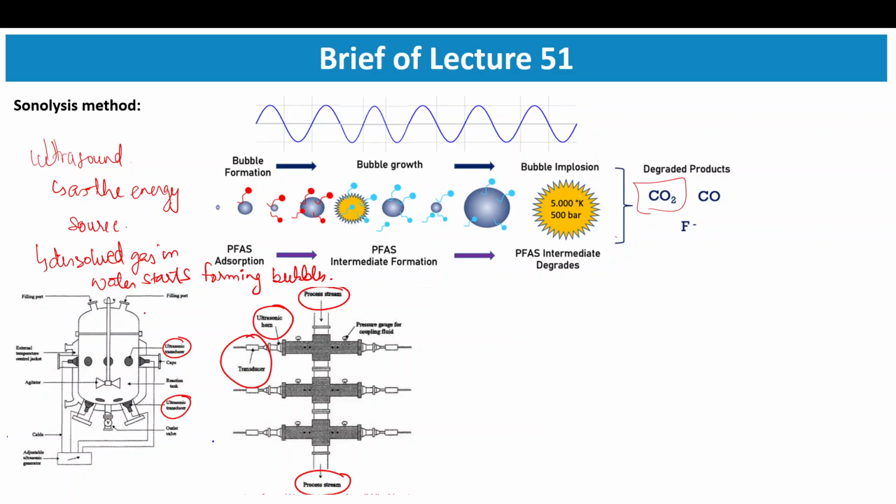In this third tank, you have process water or wastewater, and on generating ultrasound through the various transducers, you allow continuous agitation so that mixing happens. The ultrasound generated through the transducer forms the hydroxyl radical and other radicals, and it causes the degradation, and finally you will have the outlet purified or treated water.